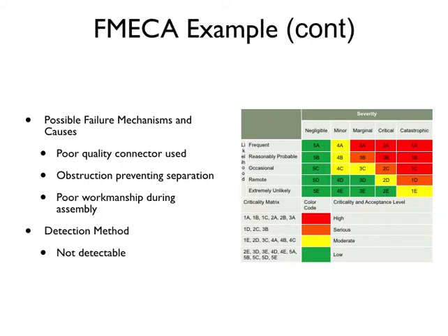In this particular case, though, this failure mode would not be detectable, so it had zero detection. Now, in this case, they were doing this via a FMECA, so they noted no detection method, but that did not play into the risk, right? Because the risk was catastrophic and extremely unlikely, so the risk was 1E, which is moderate.